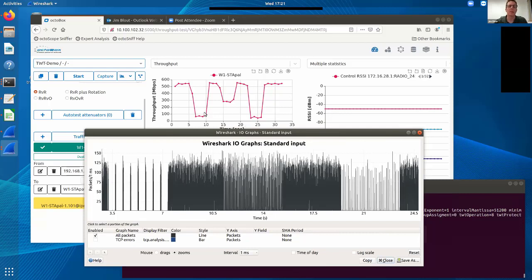So we can see that the first issued commands brought this throughput down to under 100 megabits per second. This is the one that had pretty long sleep times and wake duration: about a 524 millisecond sleep duration with a 65 millisecond transmit time, a 10 to 1 ratio roughly. The one in the middle was about 2 to 1, so we can see it affected traffic much less.